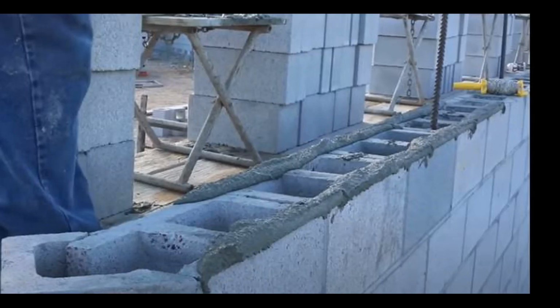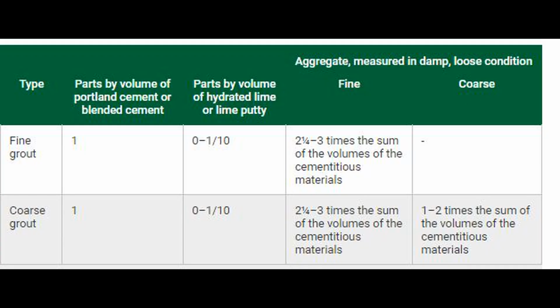Third is the grout one. Ideally, mortar and grout are classified based on the proportion of ingredients. Mortar is required to be class M, and again one has to refer to the country code. It has a proportion of 1 bag of Portland cement and 1/4 hydrated lime. A minimum compressive strength of 15 megapascal is required to be achieved. A water retention of 75% and maximum air content of 12% is required.